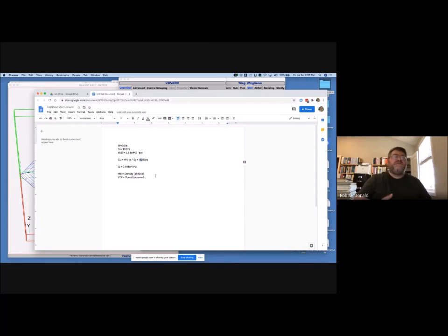So this is one of these situations where, as an aircraft designer, and also with wing area, you could imagine sending a wing walker out with a saw to cut off pieces of the wing. You could change your S during flight. That's a terrible idea. But as a pilot, if you want to trim the airplane to a different speed, if you want to change V, you can't change S. Rho is what it is. You can change altitude, but you can't demand higher rho or lower rho. You're at the mercy of rho. So if you want to change how fast you're flying, in this equation the only thing you can change is CL.